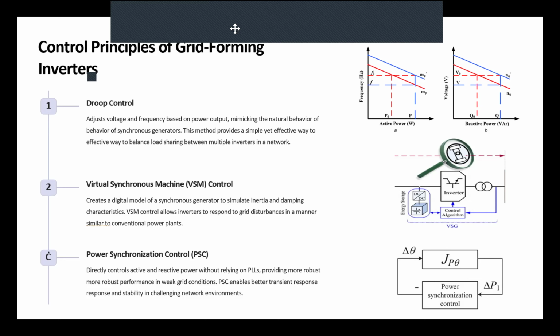How can we do that? By pushing active power into that terminal, and we balance the load and generation again. Reactive power is the same. It wants to keep the terminal at the mandated voltage. But if there is a huge reactive load on the grid, what the inverter sees is that the voltage of the grid is weak and is falling down. I have to keep it up.